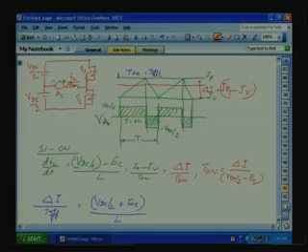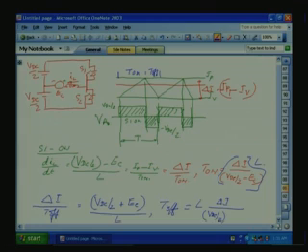Now, from this we can find out T off, which is equal to L into delta I divided by VDC by 2 plus EC. Here also, delta I by T on has to be multiplied by L, that is missing here. This L has to go here, so T on is also L into delta I divided by VDC by 2 minus EC.